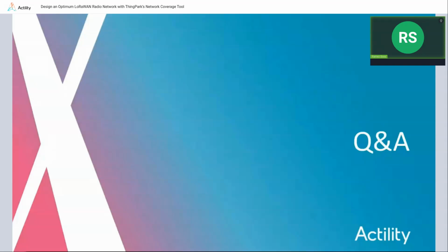Does the antenna for LoRa 868 or 915 megahertz need to be a UNB antenna? I understand UNB as ultra narrowband antenna. So to my knowledge, no. We already see many antennas that do not need to have very narrow bandwidths. Of course, they should support the whole range, whether in 868, so 7 megahertz, or in 915. In the US, for example, it covers a big range from 902 to 928. And even some antennas we see in the field are dual band. They support both 868 and 915. So I don't think that the antenna needs to really be ultra narrowband.